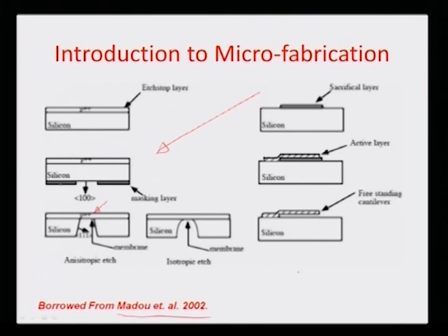You can formulate a small cavity here using resist, and so this can be used as an etch window, and there can be an etchant which is selective to P double plus, which is highly doped positive silicon on the other side, and so the material starts etching away in an anisotropic manner, thus formulating a 54-degree angle, and it just goes up to the selective layer here, which is the P double plus layer, and stops the etching process, thus creating a membrane.